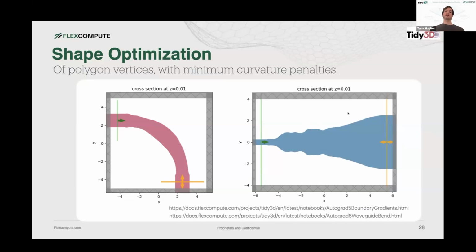And then you say, I want to optimize the taper for transmission, but I'm going to let the polygon vertices move around in maybe a controlled way or in whatever way you define. And it will automatically use the adjoint method to figure out what shifts in boundaries lead to more improvements in the objective function, and you can even apply more complicated parameterizations, such as a spline fit, or things like this. So it's a very powerful technique that we've applied in a few ways.